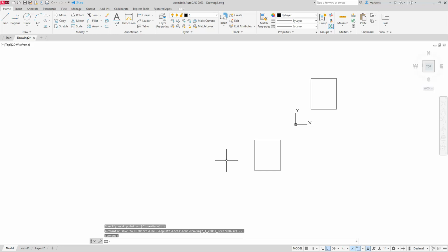All right. So that explains how you're looking at things in an absolute function. Hopefully you understand that depending on this, you have to know absolutely where the points are. Now, one other thing to remember is that each one of these methods that I'm showing you, you don't have to stick with one. By default, the line command starts off at 0, 0, right? When I put in the absolute value, it starts off as absolute, but then I can choose another value. So out of all these different endpoint methods that I'm showing you, you can choose whichever one you want.